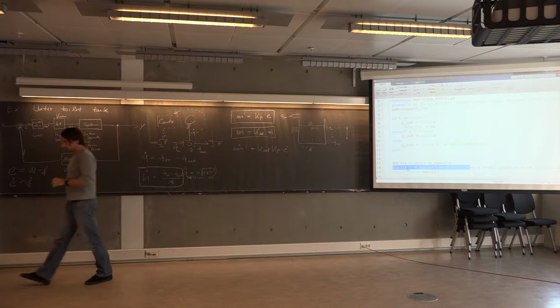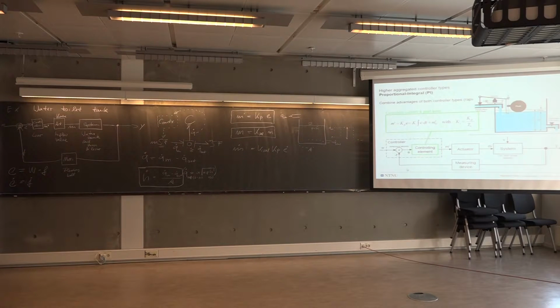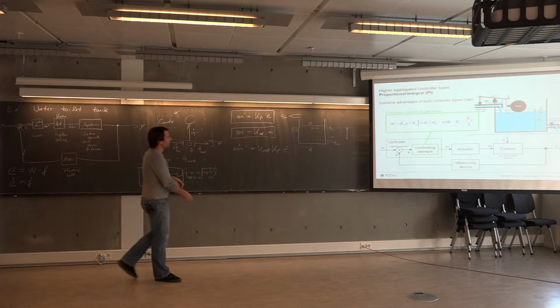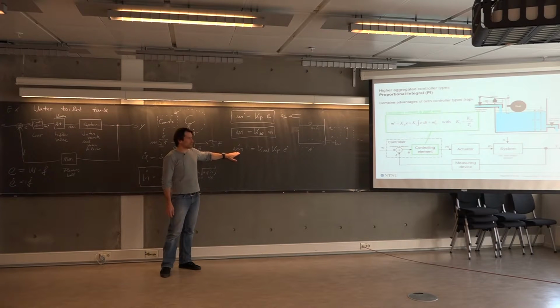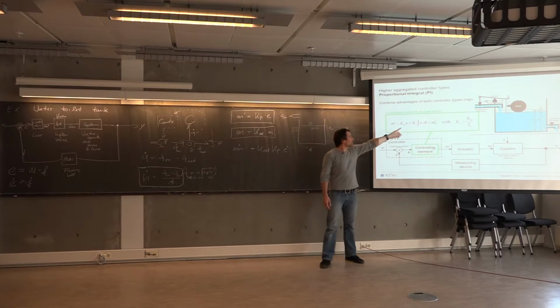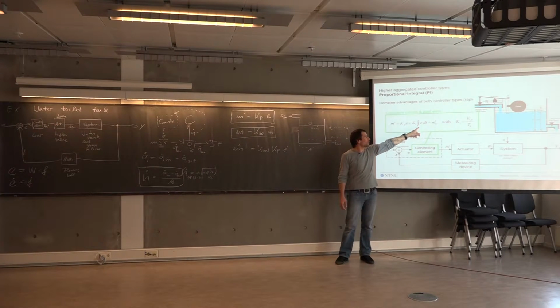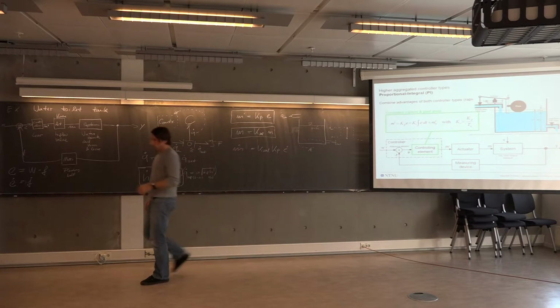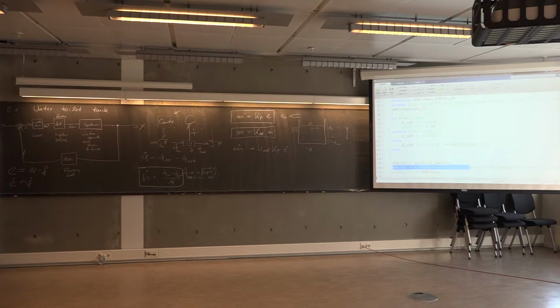Now, if we add an I term to this equation, meaning if we add this integral and use again the very same concept that we take the derivative of the manipulated variable, which provides the rate of change of the error here, and the derivative of the integral is nothing but the error itself, then we actually end up with this equation.